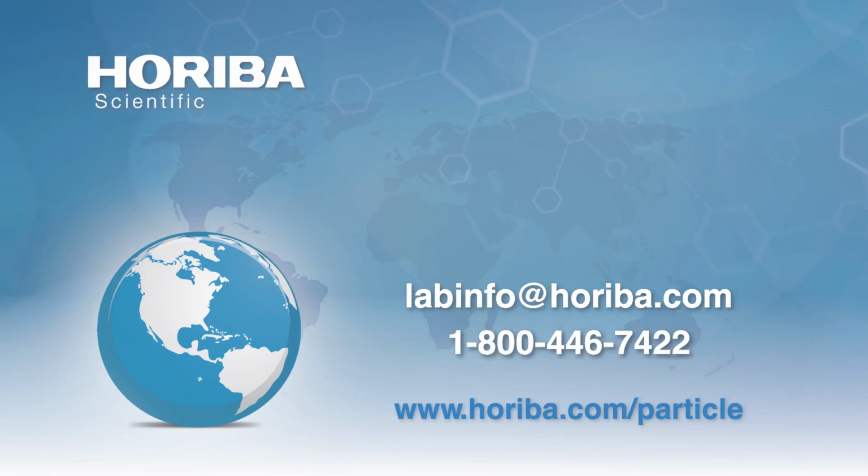This is always a good question. Interestingly, there are always lots of variables. I feel like I'm cagey about every answer, but interestingly, we can measure smaller differences in coating thickness than the size of our individual pixels, because we don't just measure a single particle, we measure thousands and thousands of particles. We can be more accurate the more time we take to make a measurement, so the longer our integration time is, and we can be more accurate in smaller product containers, because based on trials I've done